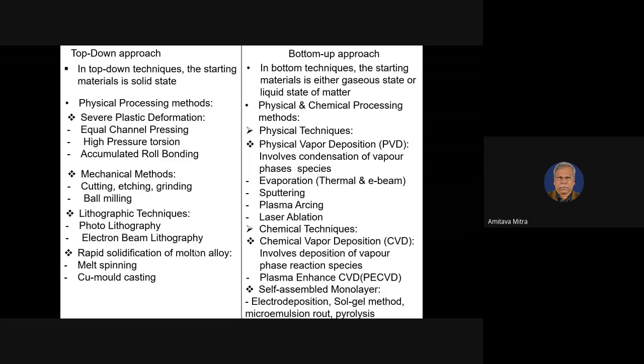Durga, can you comment on it? Yes. In graphene, what is special is that you make it from graphite, and graphite has a two-dimensional layered structure. There is van der Waals interaction along the z-axis, and in the plane it is covalent bonding. The carbon-carbon bond is covalent, so that is much stronger. But along the z direction, it is a van der Waals interaction, so it is easy to peel it off. So you can make a 2D layer, and in the third direction, it's a very weak bonding. If the material has such layered properties, then you can exfoliate and prepare these 2D materials.